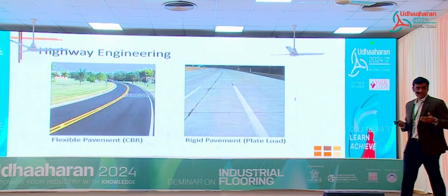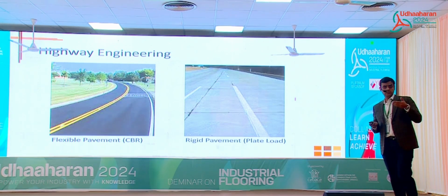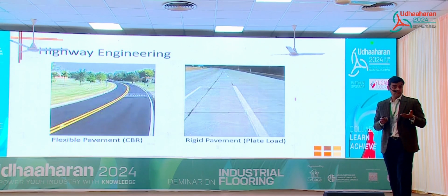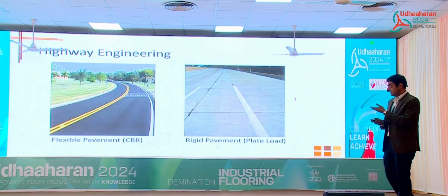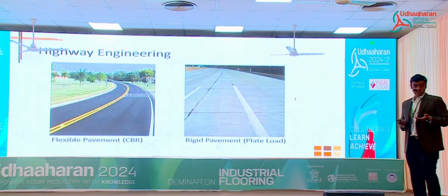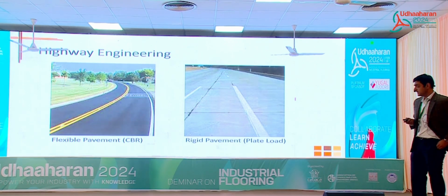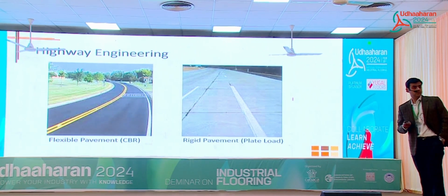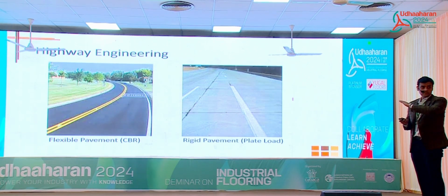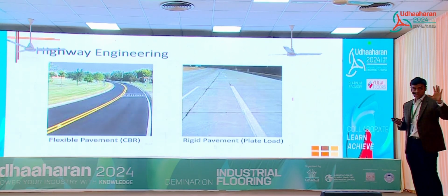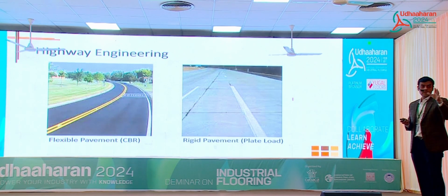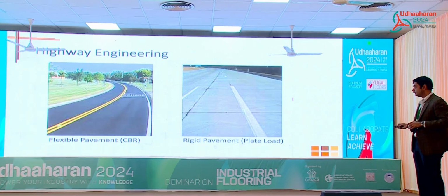So we'll take a step back. Actually, a lot of soil engineering or concepts of earthwork that we use in flooring are actually derived from highway engineering. And there are two kinds of roads that all of us are aware of. One is a flexible pavement or a bitumen pavement. The other one is a rigid pavement or a concrete pavement. The design principles of both of these are different, so we'll go over both of them. And both of them have value when it comes to flooring.